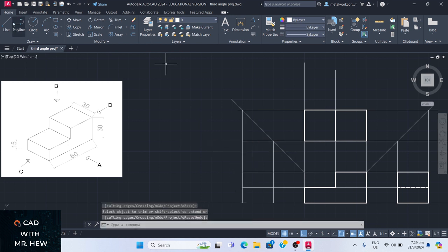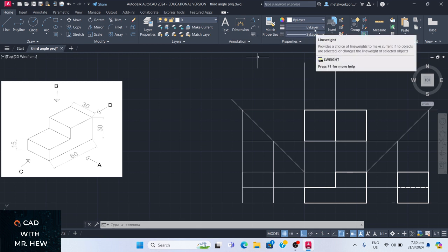So we're gonna draw a line over the object there, the end elevation, so we can darken it. Well, not darken it, but change the line width to 0.3 millimeters. So if you were using the traditional T-square and set square, you would use the 3H pencil or the 2H pencil to darken it. So this is what we're actually doing now in the AutoCAD software. Well, the equivalent, all right?